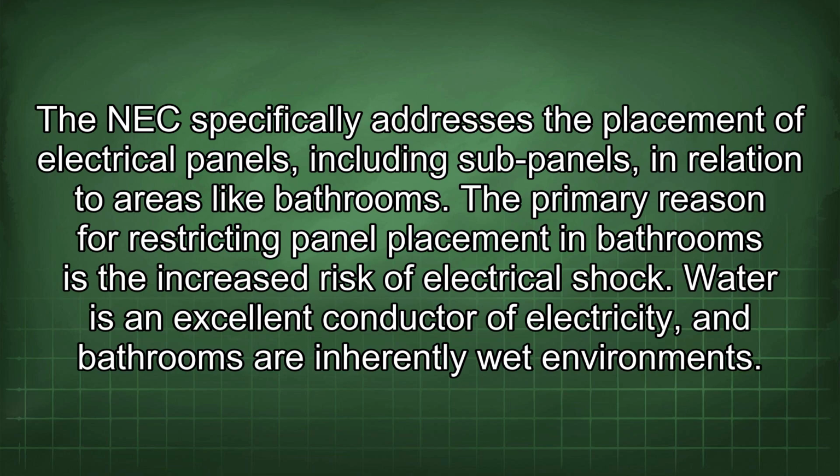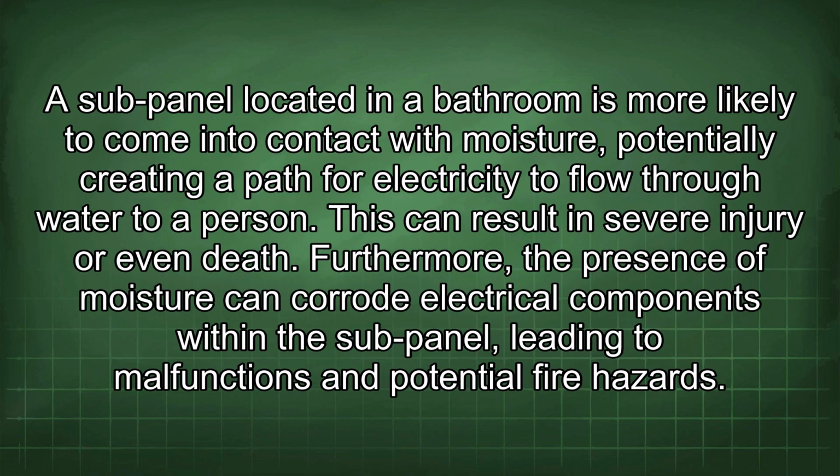The primary reason for restricting panel placement in bathrooms is the increased risk of electrical shock. Water is an excellent conductor of electricity, and bathrooms are inherently wet environments. A sub-panel located in a bathroom is more likely to come into contact with moisture, potentially creating a path for electricity to flow through water to a person. This can result in severe injury or even death. Furthermore, the presence of moisture can corrode electrical components within the sub-panel, leading to malfunctions and potential fire hazards.